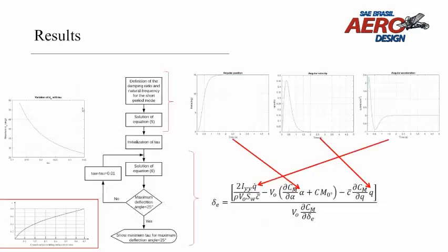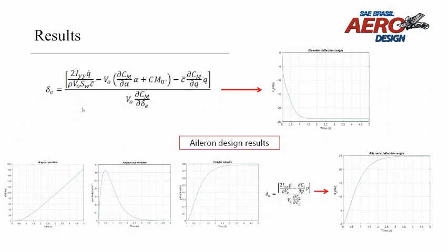The results will be presented in the form of a sequence as well as the block diagram of the iterative process. First, the position function is obtained. Then it is differentiated once to get the velocity function. The velocity function is differentiated to obtain the acceleration function, and these three functions are substituted into the solved dynamic model. Parameter tau is iterated until the condition is achieved. The results for roll dynamics are presented as a sequence, and we can notice that the maximum deflection condition